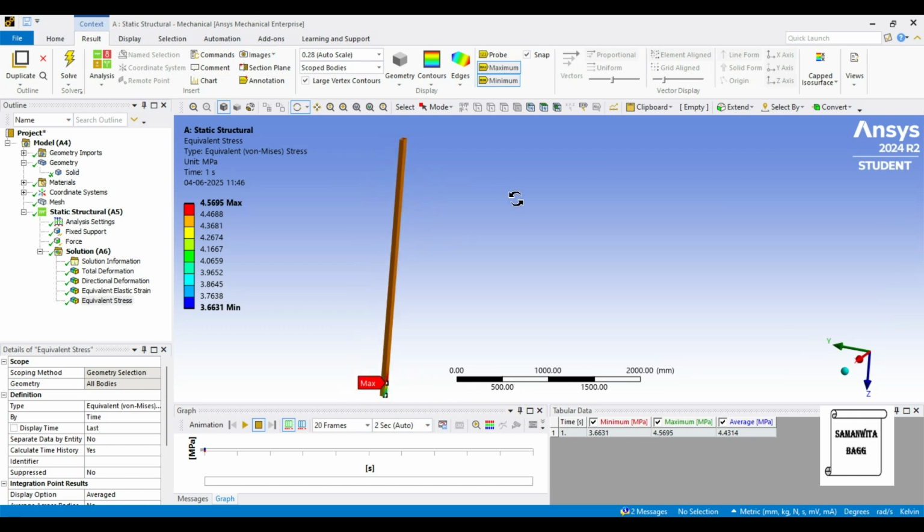If you don't want to change the cross section, maybe if the constraint is with the cross section, you can change the length, or if you can change the material, that is also well and fine, which will have a better yield strength. Or you can shift to what we will discuss next, which is CFST column. So there are many other options also available if the constraint is of dimension or load or the length, something of that sort. So you can just go about with what is variable and you can change that.